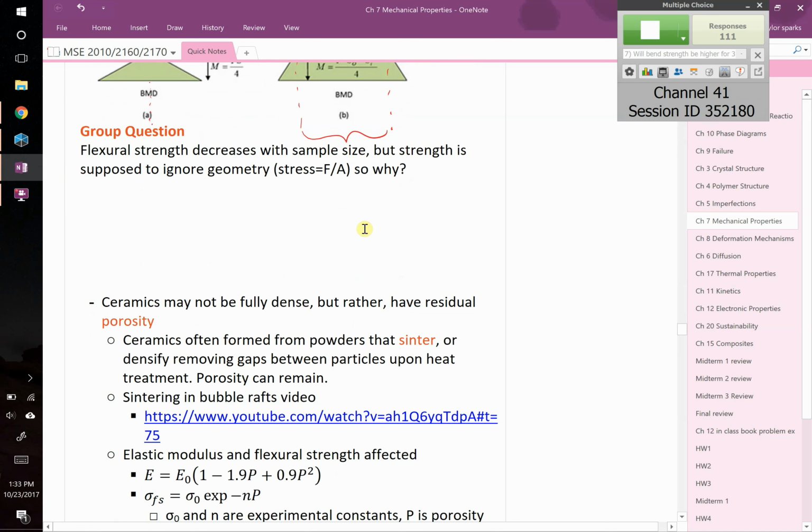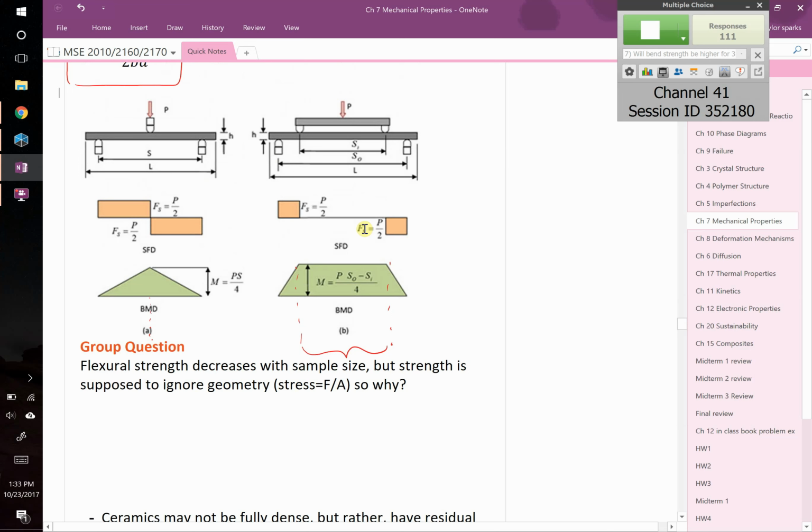Question? Yeah. Could you just remind us the difference between stress and strain? So if you take a sample and apply, say, a compressive stress on it, meaning it's happening perpendicular to the faces of your material, you will cause this material to change its initial length. In this case, it's going to get smaller, right?